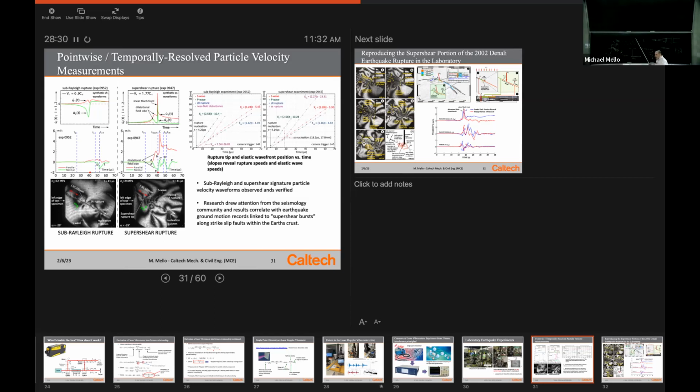Not every polymer is birefringent. You have to have a birefringent polymer that will aid in the creation of these fringes. These fringes are literally contours of maximum shear stress. That's literally what they are. That's why they light up when the S wave comes by, okay? So theory of that interferometer would show that these fringes correspond to fringes of maximum shear stress, okay? We don't have time to discuss photoelasticity. If this was a dedicated course in optical techniques, we'd go off and say, let's study photoelasticity now. So we just put that on the shelf, okay?